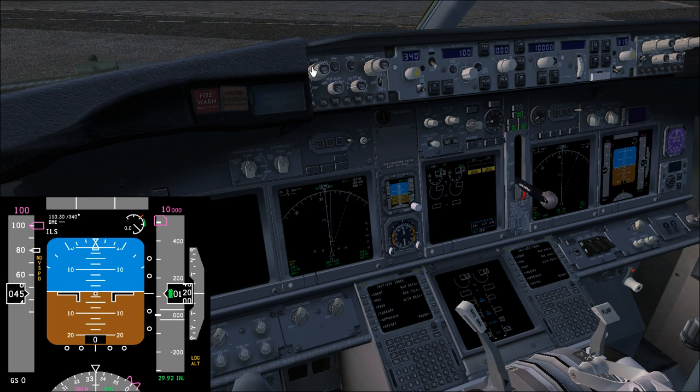Now I will reset the system. If you go to radio, the indicator is always displayed, but it is only selected by a triangle, not a triangle with a line. This is because other information about the decision height will be taken in case of radio.